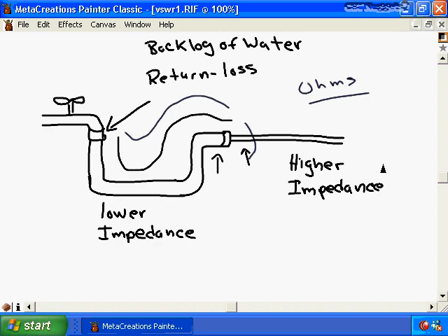So to avoid these problems associated with voltage standing wave ratio, or VSWR, which again is mismatched impedance, is simply to use cables and connectors of the same impedance, which again is measured in ohms. So you want to make sure that all of the cables and connectors are rated at the same ohm level. And also make sure that there's a nice, tight, strong connection between all of the cables and connectors as well.